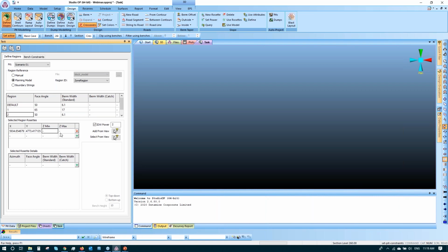So starting with some hands-on here, I have to choose my lowest elevation. Over this control bar here, we can play with our benches. Our benches can be displayed over here, so I can quickly see which is my lowest bench, which is the minus 70 RL.